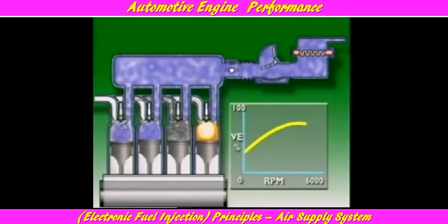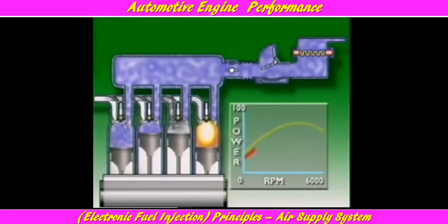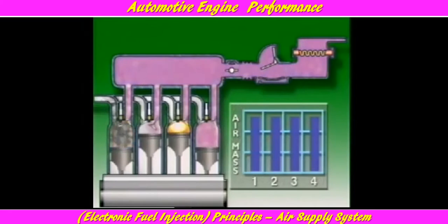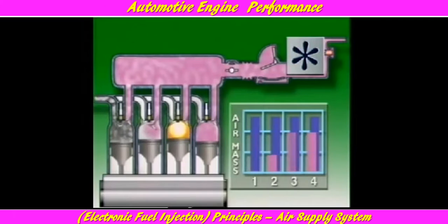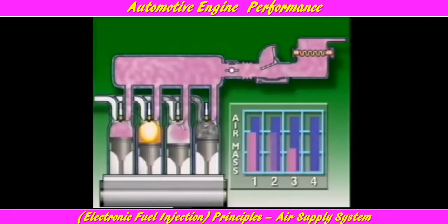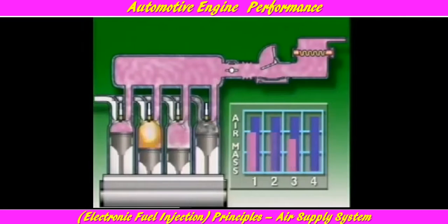The more air crammed into the cylinder, the denser the air-fuel mixture when ignition occurs. This increases the thrust on the piston and increases engine power output too. The temperature of the air influences how dense the air-fuel mixture will be. Cold air is denser than hot air, so it has a greater mass in any given volume.